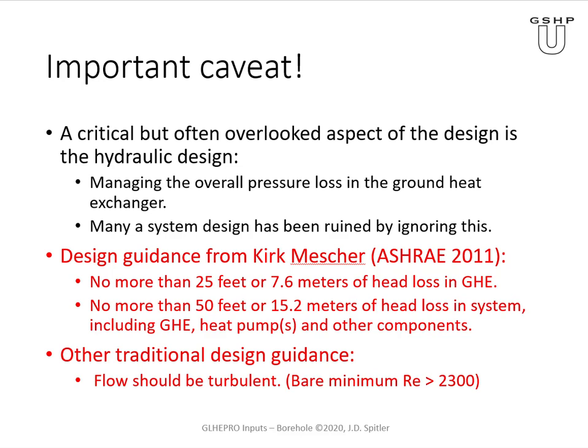One important thing I'd really like to point out to you, and this is really important if you're a GLHEPRO user, is a critical but unfortunately often overlooked aspect of the design, which we call the hydraulic design. In other words, what's the overall pressure loss of the ground heat exchanger and the system? And I will tell you that many a system design has been ruined by ignoring this.